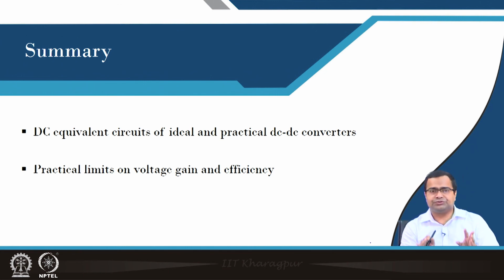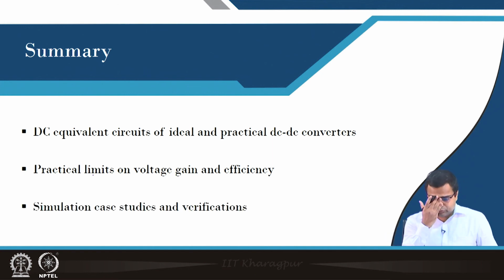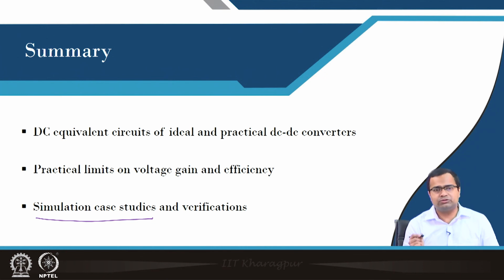But even if we choose a smaller on-state resistance and DCR by using a costly inductor, still this voltage gain will be limited when the load current increases. Okay? So, that means there are practical limits, and it is not recommended to use an ordinary boost converter for a high voltage gain application. And we have shown a few simulation case studies for a synchronous buck converter, and the same thing can be carried out for boost as well as non-inverting buck boost, and we can verify.